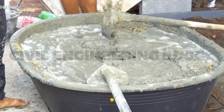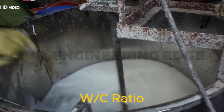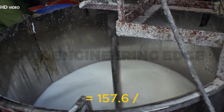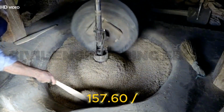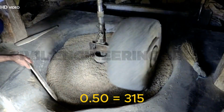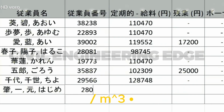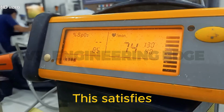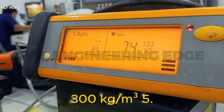4. Cement content calculation. Cement equals water divided by W/C ratio, equals 157.6 divided by 0.50, equals 315 kilograms per cubic meter. This satisfies the minimum requirement of 300 kilograms per cubic meter.